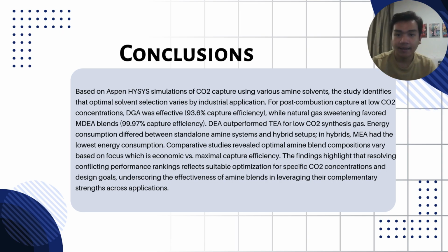To conclude, based on the Aspen HYSYS simulation of CO2 capture using various amine solvents, the study identifies that optimal solvent selection varies by industrial application. For post-combustion capture at low CO2 concentration, DGA was effective, with 93.6% capture efficiency. Energy consumption differed between standalone amine systems and hybrid setups. In hybrids, MEA had the lowest energy consumption.